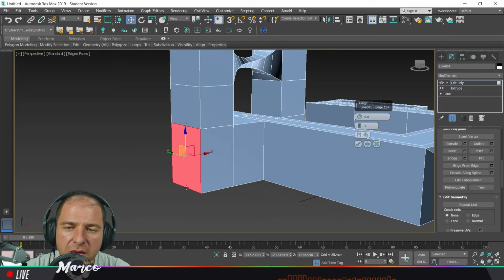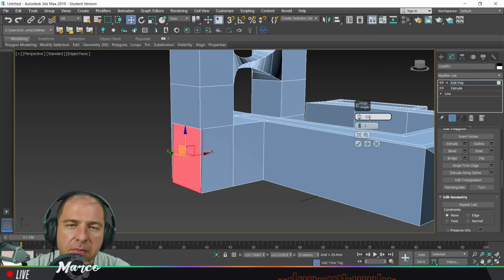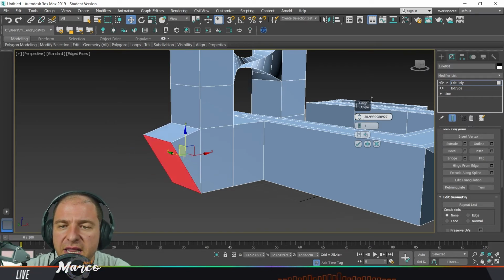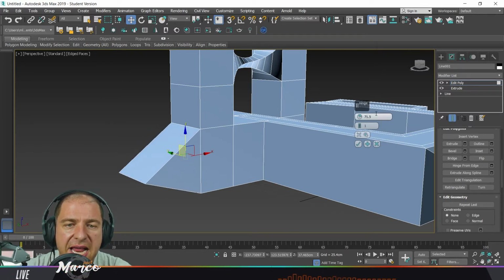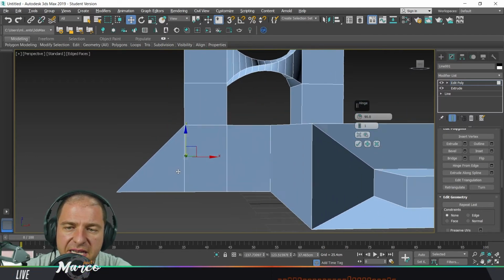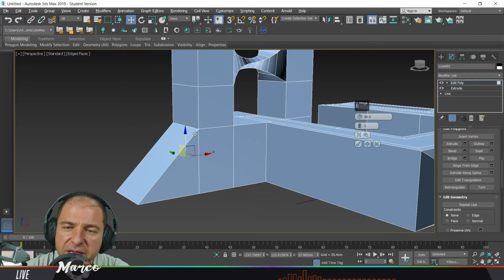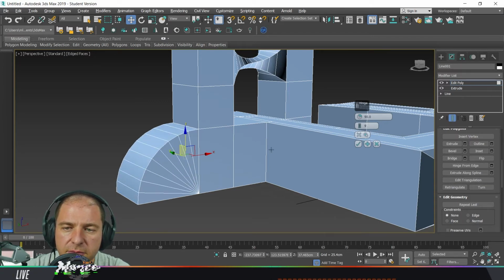Let's say I will pick this one, and now if I change the angle, what happens is that my selected polygon will be rotated by using that edge as rotation axis. And then if I want, I can not only choose the angle, I can even type it if I want something more precise, but if I increase this parameter that is edges, instead of having these flat connections, I can have a rounded result.